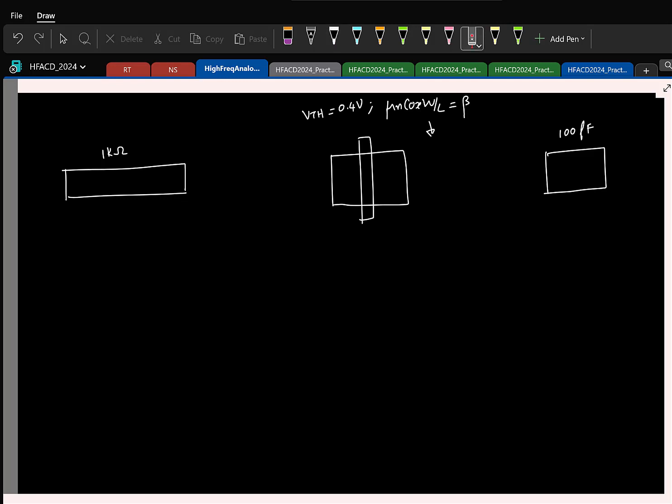Now in the same design, let us say I have an identical resistor placed close to this. What do you expect the value of this one to be? You expect that it should be 1 kilo ohm, but as I mentioned in the beginning of the class, there are no two elements which are truly identical. There will be some kind of mismatch.